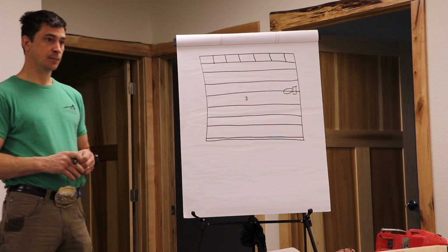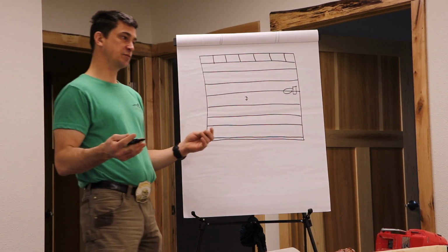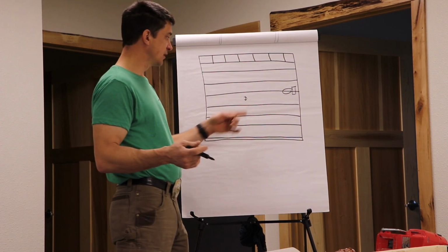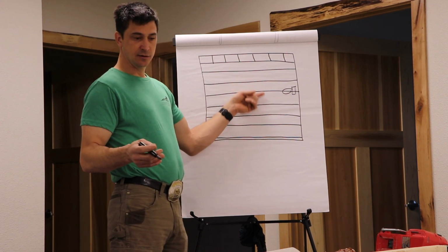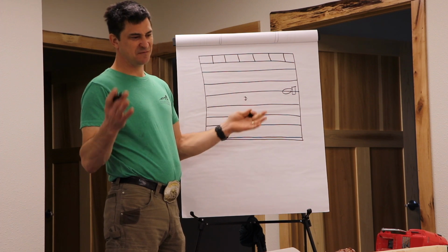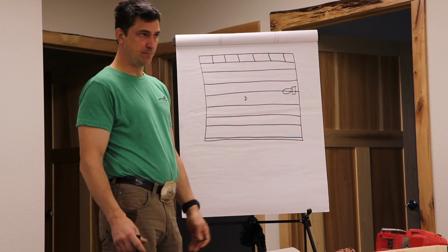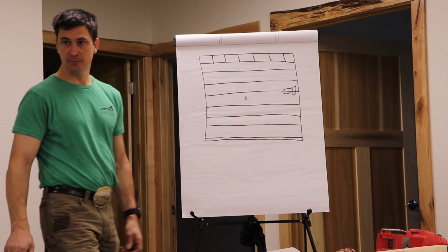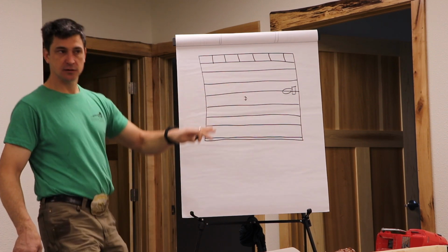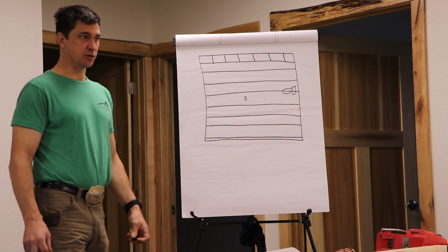Okay? So then you want to look at the span rating on your sheathing. But if you're using a 3/4 inch floor sheathing, you can get up to like 20 inches without a problem, and it won't get like spongy like a trampoline in between the joists.